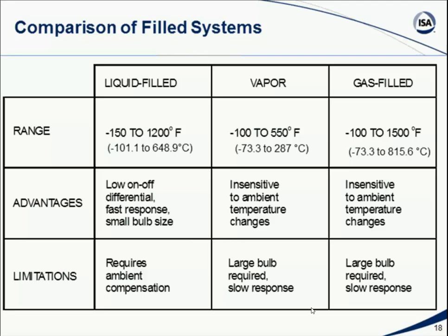An important one is range. If you look at the liquid-filled, you'll see that liquid-filled can go down to lower temperatures than the other types. On the other hand, if you need to go up to higher temperatures, gas-filled tend to allow you to go to a higher upper temperature range. There's also an issue of speed of response. If you look down at the limitations, the liquid-filled has a disadvantage. It's affected by ambient temperature.